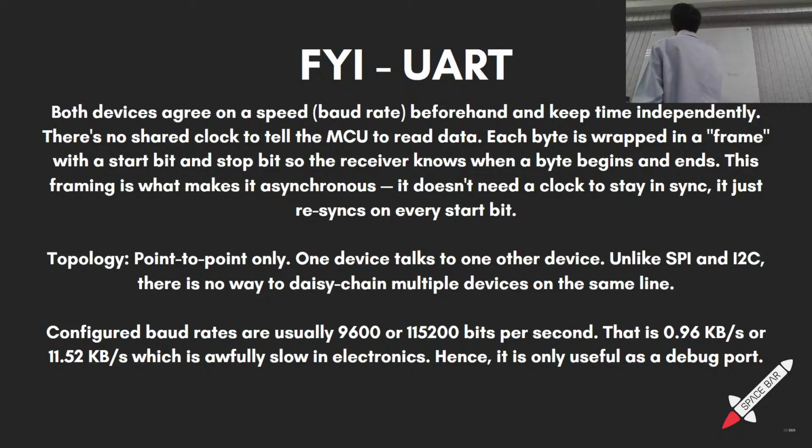Okay, next is I squared C. I squared C, unlike UART, has 2 pins. One for bidirectional data and one for clock. So unlike UART, which relies on the clock of the receiver and of the host and device, I squared C has a clock and data line.